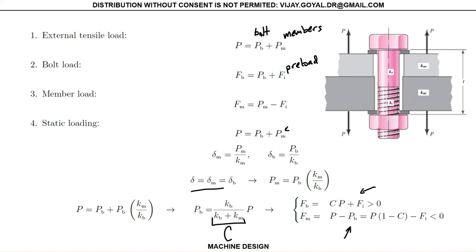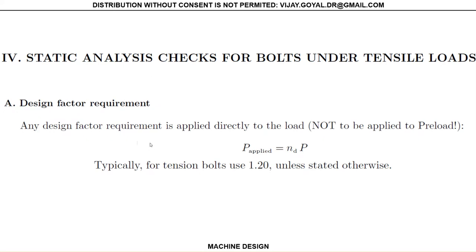Then the second thing we want to do, once we have our load analysis, is apply our design factor. Here, the standard design factor is 1.2. You want to maintain that every single time. Some companies have 1.15, 1.5, 1.4, for different applications. So this is the base. And remember, if you have any additional factor, then you will multiply this times this. So this is important. Just remember, as we did for the case of springs.